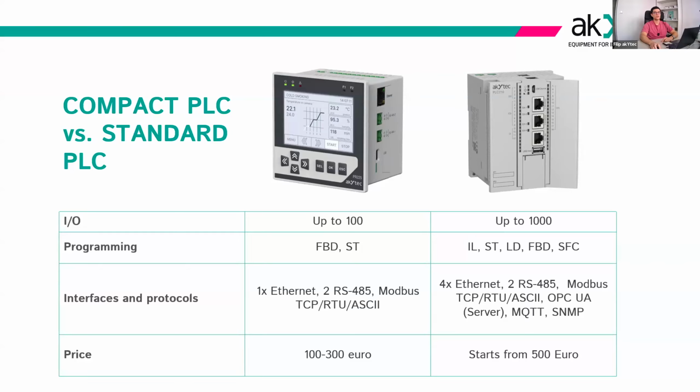often requiring specialized training. PR controllers feature one Ethernet port and up to two RS interfaces, offering all essential connectivity for typical automation scenarios. And on the other hand, traditional PLCs may include additional ports and protocols, which are great for installation, but often unnecessary overhead for compact systems.